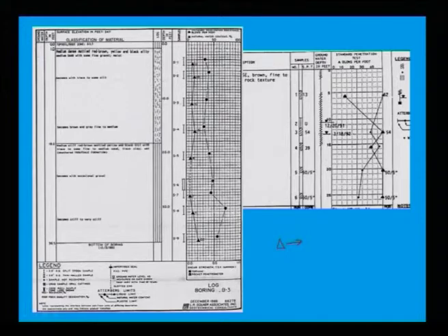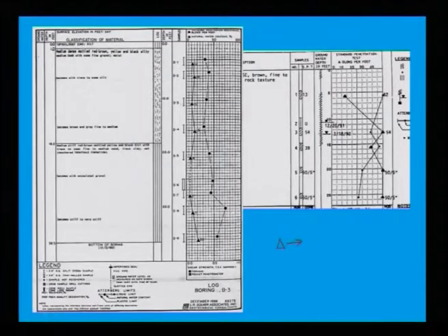So what is the advantage? At first glance, the site engineer, the design engineer, instead of taking N values, can see how the profile varies. If you look here, almost N is constant between the depth of say 2 feet to 20 feet, the penetration value is almost the same.